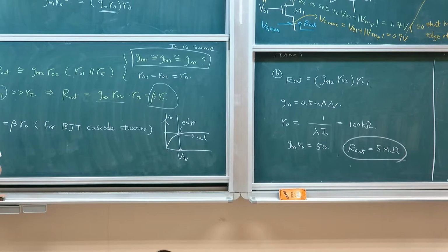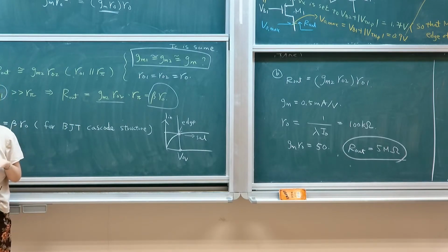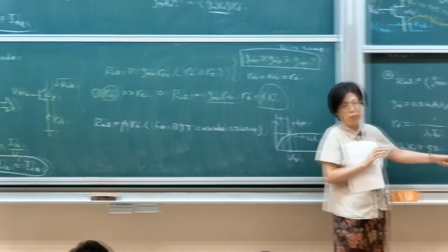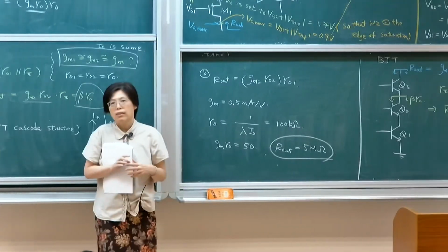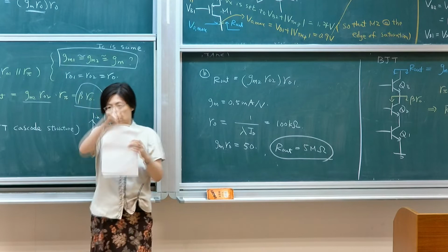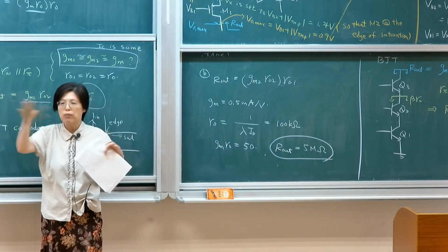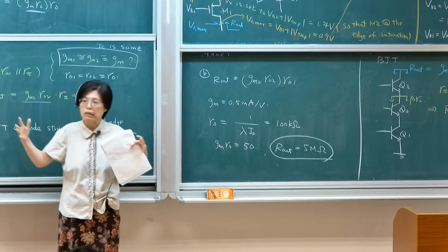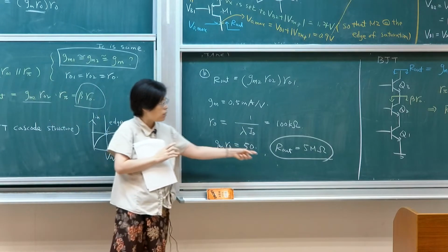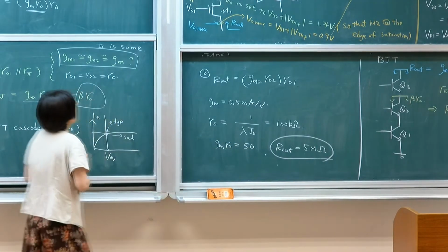If you ever did any tape-out, and I give you a resistor model file, you will see that creating a 5 megaohm resistor is essentially impossible, or very area consuming. You use snake-like routing to get very large resistance, and you need a lot of routing area for that to be realized. So this is a very powerful tool.